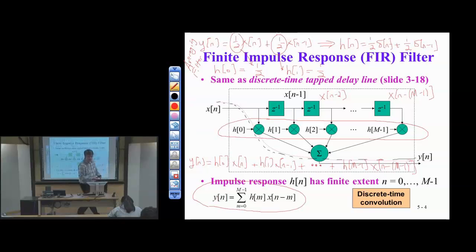All right, so what can you do? So when you design an FIR filter, you get to pick the number of coefficients, and you can do this on a couple of cases manually. So if you need a really simple averaging, a low-pass filter, you can use the averaging filter. If you want a simple high-pass filter, what would you do? First order difference. And for a first order difference, H of 0 is, if we normalize it, H of 0 is 0.